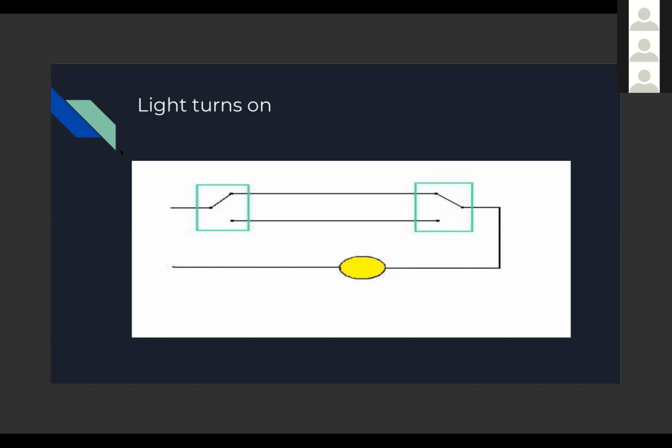And no matter which one, so right now in this diagram, both of his switches are in the up position, but that upper wire makes that connection. And so this is what's bizarre about a 3-way switch. And when you start wiring houses, you'll learn about this, is that you've got to wire one switch to the other switch. Notice only one switch goes to the light bulb. Only one switch is connected to the light bulb, and in this case, it's the switch on the right-hand side.